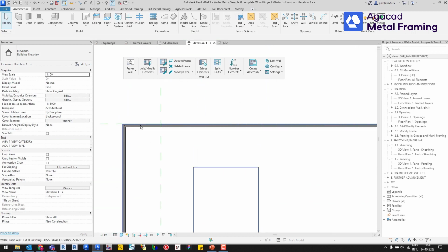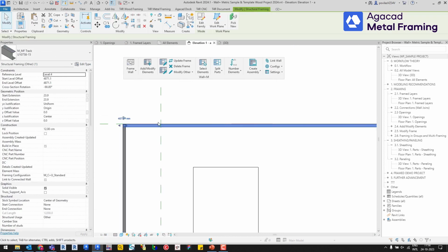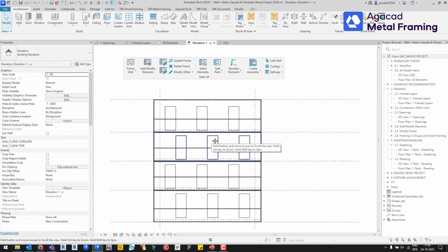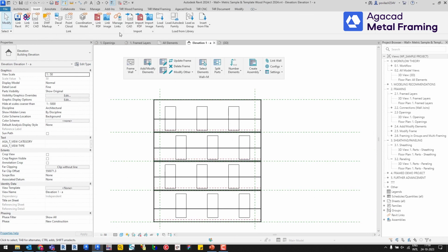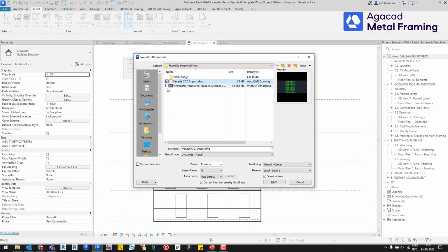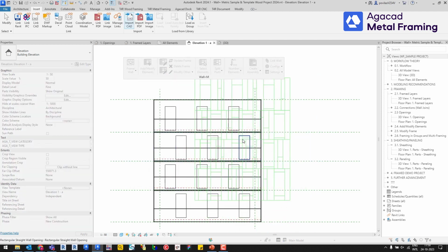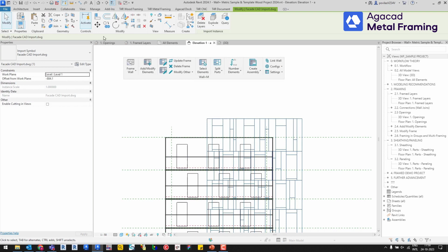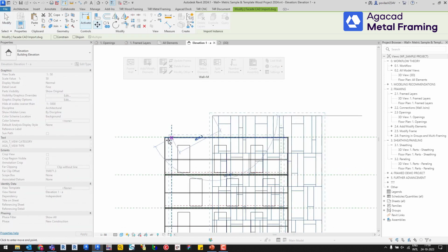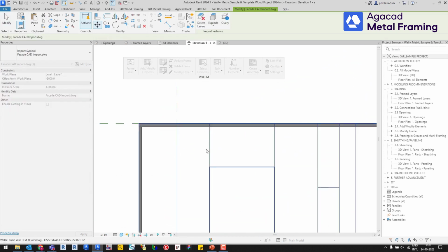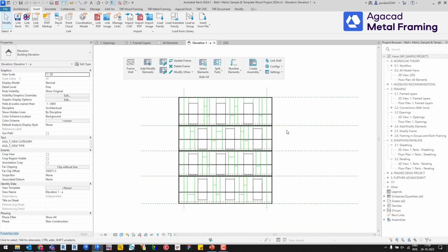So in this example, I'm using Wall+M for light gauge steel framing. I'm framing those 4 walls I have modeled with openings, and I'm only framing just to get at least one framing element. In this case, I'm getting side studs, top bottom plates, and horizontal bracing. Now I'm importing the DWG that contains my desired layout for the framing members for those walls, right?